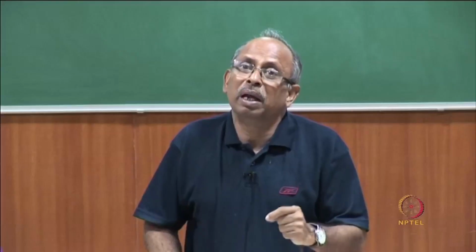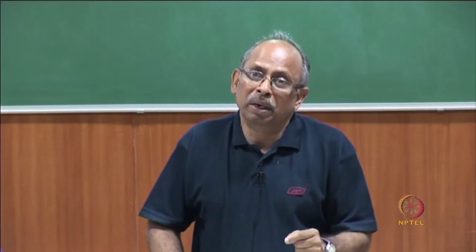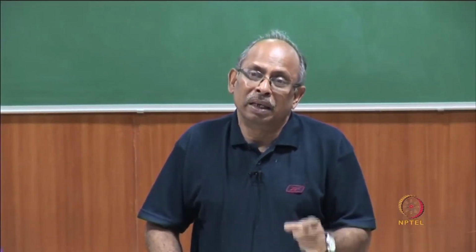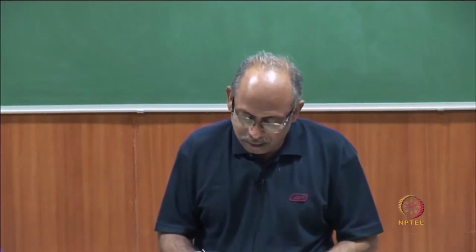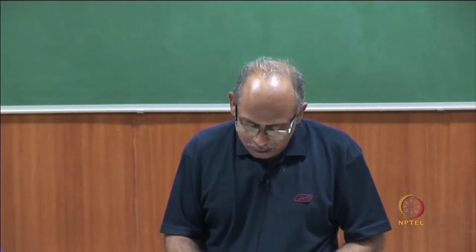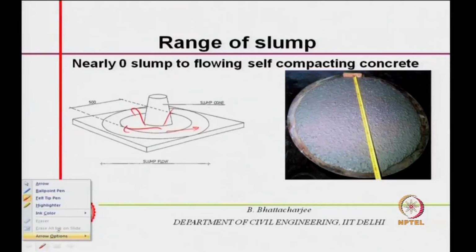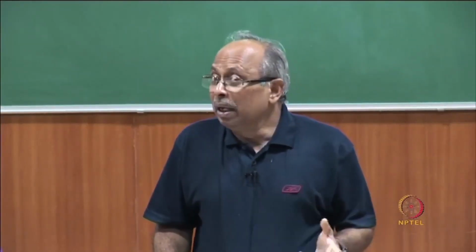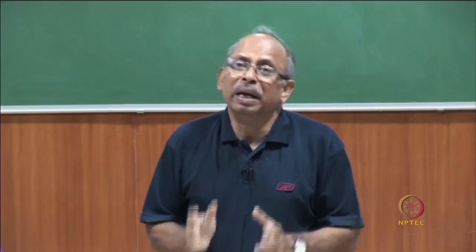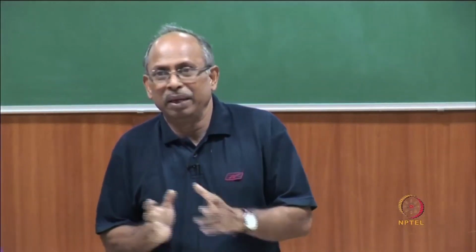And I also talked about mini slump earlier. If you remember, we talked of the mini slump test in the context of admixture compatibility or selection of admixture, etc. Mini slump test for paste, right. That is essentially related to the empirical methods for workability. As you can understand, pumping of concrete will be related largely to the slump finally, okay, you can't do the other one.